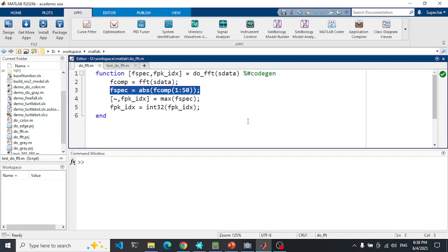Please understand that when the fast Fourier transform processes the data, in the form of a sequence of samples from the sensor, the output is a sequence of complex numbers. The size will be reduced by half because of the reflection. When we perform the fast Fourier transform, the spectrum will be half of the original data.